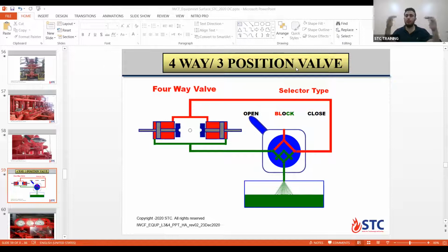But we need to wait for pressure changes. If the accumulator stays the same and the annular stays the same, in this case there is a blockage, okay? If the accumulator decreased and the annular decreased and is still decreasing, this gives you an indication there is a leak. But what will happen if you need to make the function, okay? Your pressure stays constant and the light didn't change. This gives you an indication that the 3 position 4-way valve has been stuck, okay?